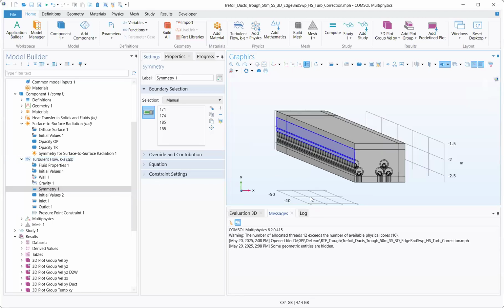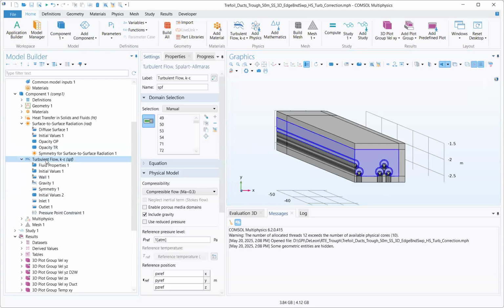So once we configure these extra settings, we run the simulation, but you need to know your fluid flow regime. Do not assume it's laminar when it could be turbulent, right? Because if it's turbulent and you try to use a laminar flow solver, you're gonna have problems. If you use the correct solver, you're gonna get convergence quicker, and you're gonna get accurate results. So there are equations to compute and analyze to know which.